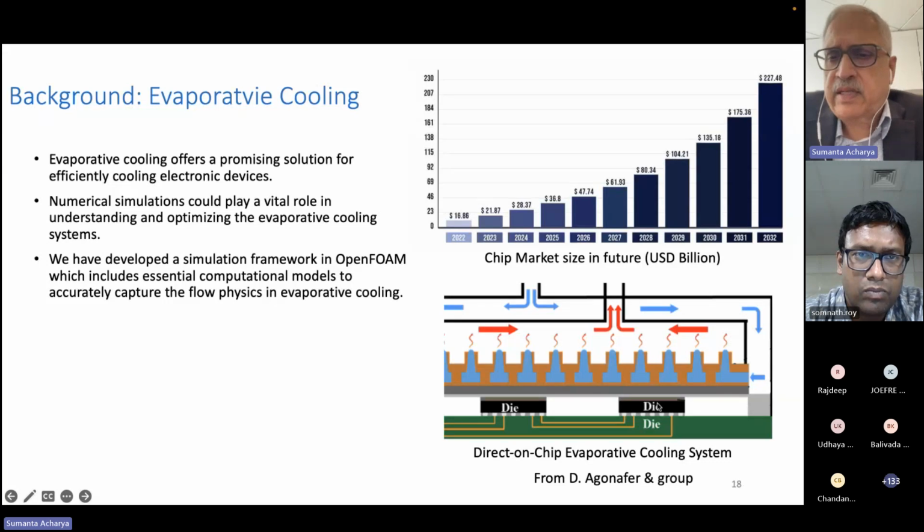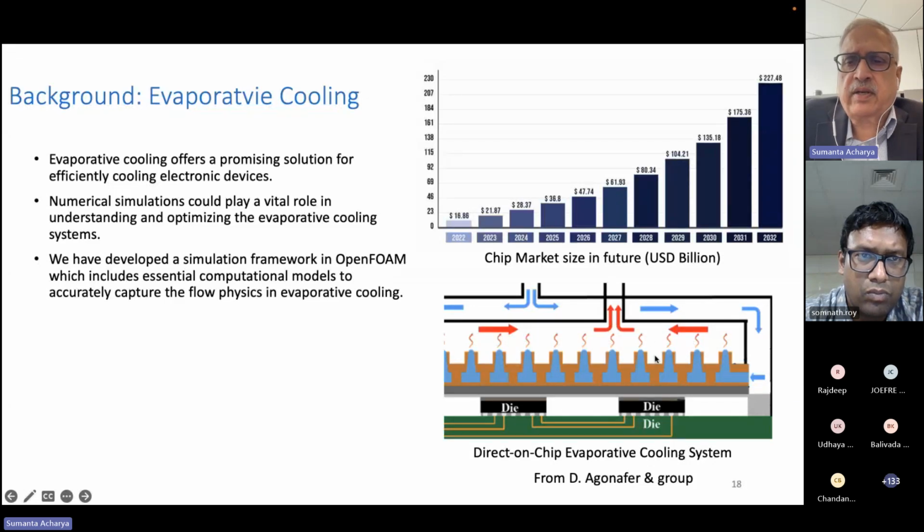Here is a configuration of liquid cooling that we are doing with support from the Department of Energy and the ARPA-E programs. Basically, the idea is to have an array of micropillars on this die. There is a thermal interface material here. There is a heat spreader here. This is a copper block, and etched into this copper block are these micropillar arrays. Liquid coolant is being delivered.